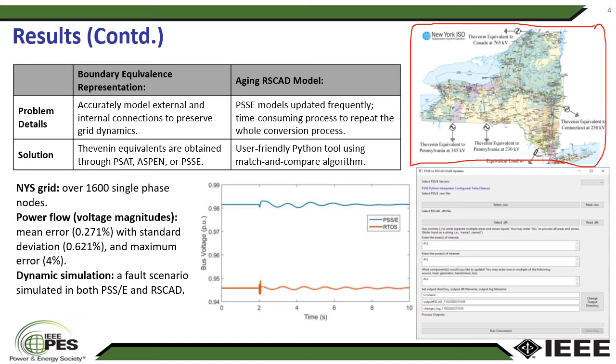Also, due to aging of the RSCAD model, as PSS models are updated frequently, we proposed a user-friendly Python tool which is based on a match and compare algorithm. The tool compares what is updated in the PSS and reflects the changes on the RSCAD model.